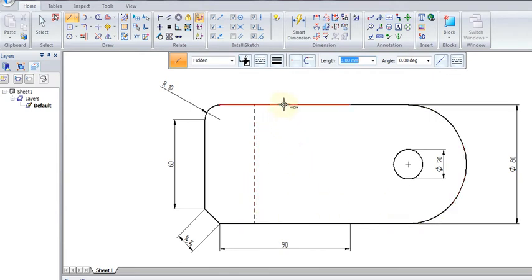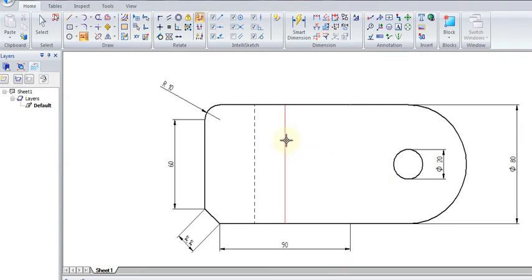Let's again create another line here, but this time let's stop it about halfway. Release the tool. If we have a line that can be extended to another intersection or the next perpendicular line, instead of having to draw the line all the way, we can actually use the extend to next tool. What this does is basically extend a line to the next closest intersection. So let's click on that, and let's click on our line. You see, if I put the cursor over the line, it shows you a preview of the extension. So I put it over my line, left click, and the line's complete for us automatically. It's a productivity tool, but not always necessary.